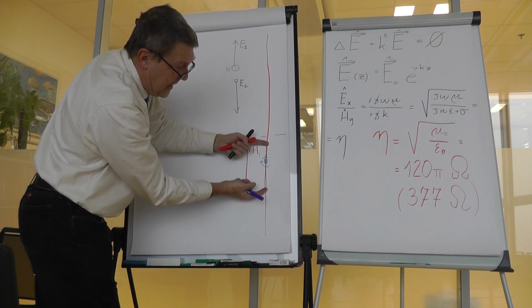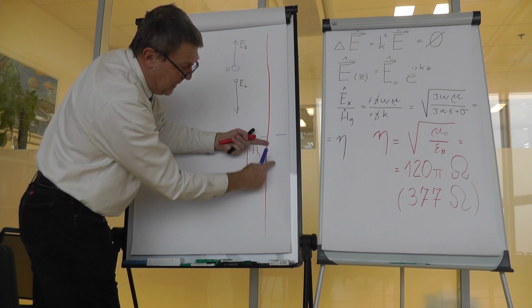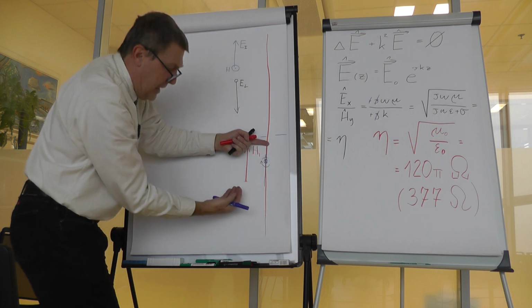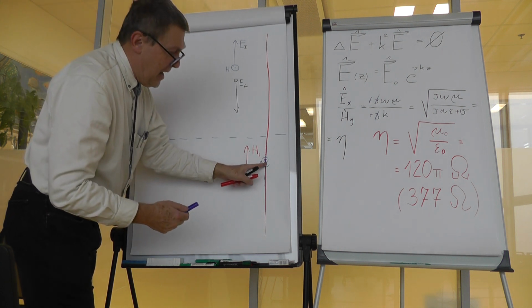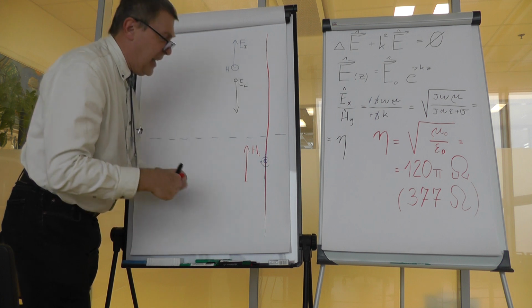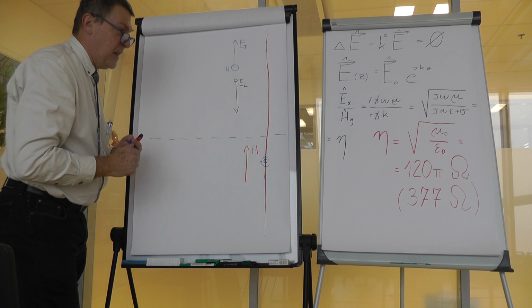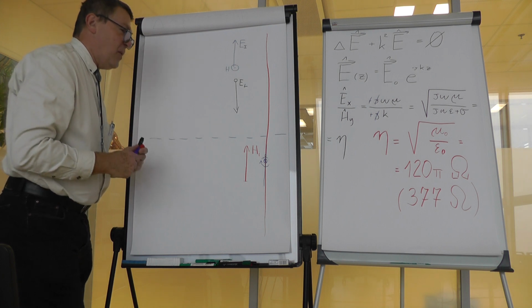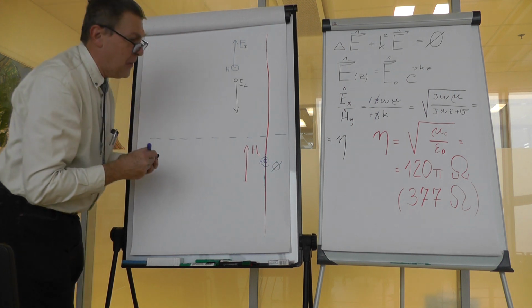Each meter of the current has to serve 1 meter of flux line upstairs and 1 meter of flux line downstairs, or left or right. So we need current density 2 times the incoming magnetic field intensity, which then would result in 0 magnetic flux here.